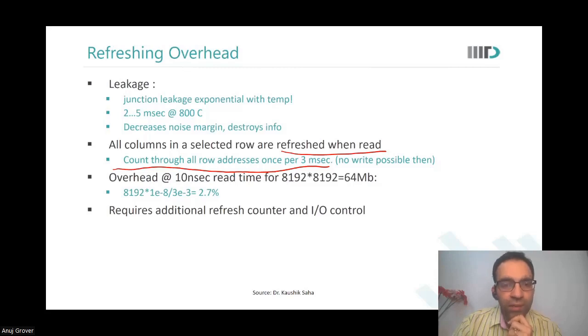What do you understand by read time? I mean, without the refresh, only regarding the read time. What is read time according to you? Sir, the read operation should be completed, starting from the word line to the end where we read the capacitor value. I think that should be the read time. Yes, exactly. That is what it is. So we don't have the refresh time in this. Is refresh time different from read time?